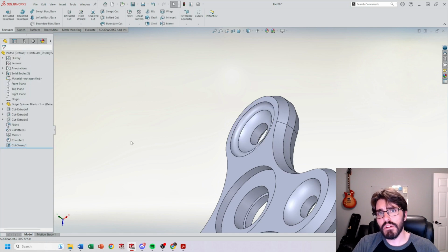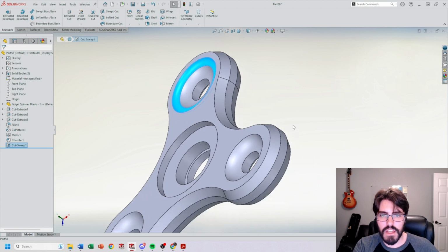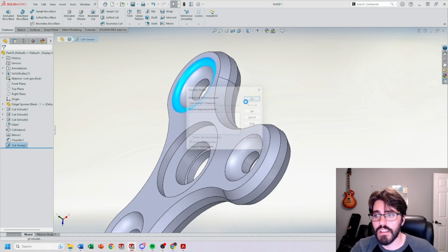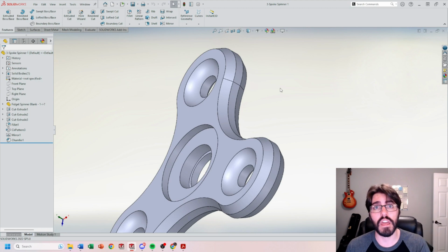All right. So if I want to take this one step further, I'm going to go ahead and click on that cut sweep one, and I'm going to delete it and get rid of it. So now we're going to do a user-defined profile and project it against a path to better control the offset of a tool or a ball mill while utilizing the swept cut command. Now, this is going to take a little bit longer for us to set up. However, I think that this is the best case use scenario for industry because we can actually offset that tool so it's not fully engaged at the tip or the quadrant or the entire edge.